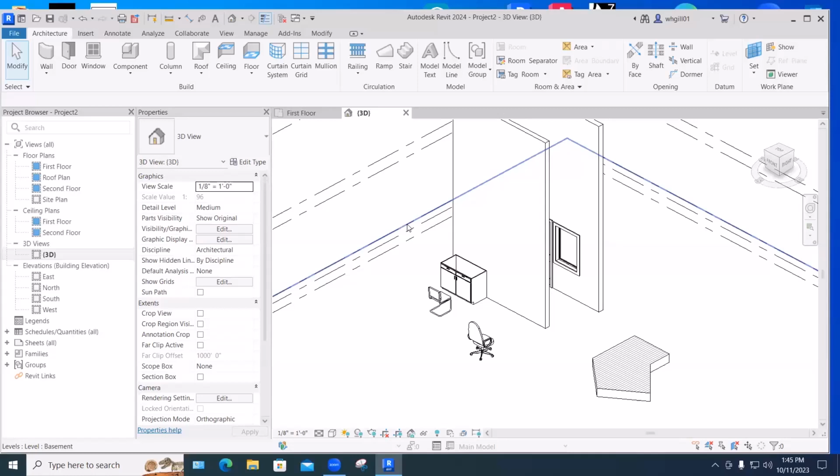And you don't want to save it back to the same folder as the families that come from Autodesk with Revit 2024, because when Revit 2025 comes out, it's going to have a new set of folders for furniture. You'll probably get rid of the 2024 ones and delete those folders, and you don't want your stuff disappearing. As Revit 2024 leaves your computer, you don't want your families to go with it. So that's how you load one family at a time.